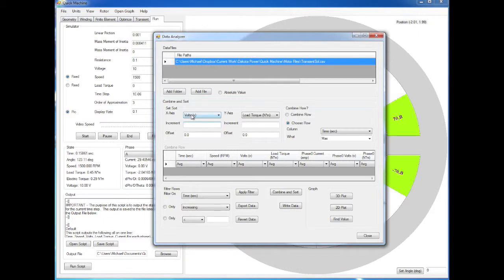That's going to define my first part of my grid. And I'm going to have an increment of 1, because that's the way I incremented my voltage in the driver control script. Now, I don't want my grid to be from 0 to 1 on voltage. I actually want it to be kind of in between that. So I want it to be from 0.5 to 1.5. That's going to define my nice little box for one of my squares.